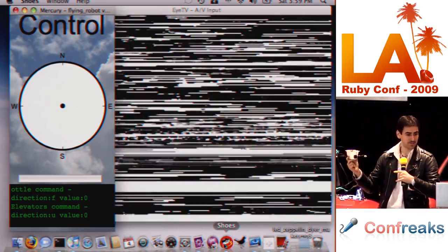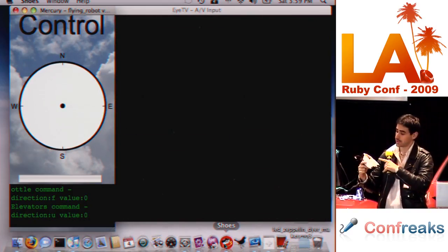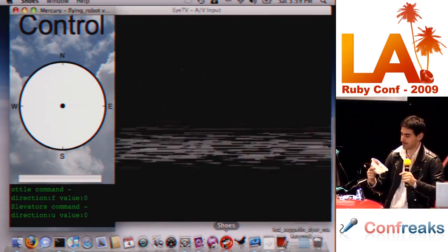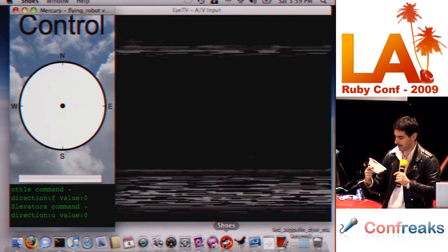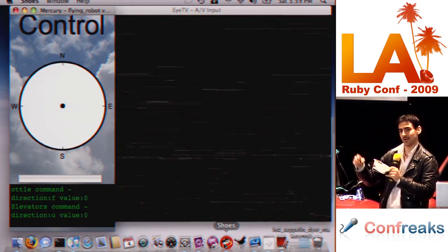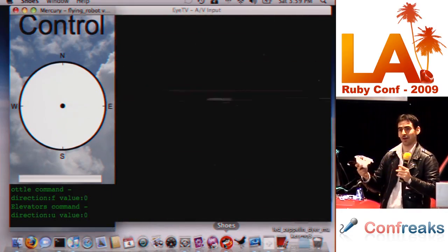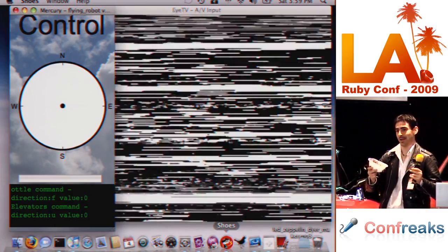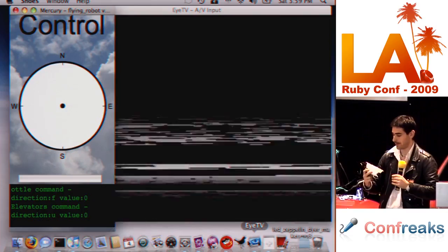Yeah, well, that's a breakdown of the inside. And also, we can use the XP modem, just another little fun tidbit. Through a lot of trial and error, we discovered we can program the board wirelessly using the XP modem. So if we want to upload new code while it's in the air, we don't have to pull it out, connect it to USB, et cetera, et cetera.